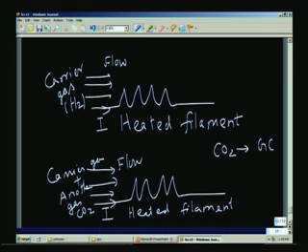So, the carrier gas, for example hydrogen, has a very high thermal conductivity, as you saw in the previous slide. We showed the high value for the carrier gas, but if I put a small amount of CO2 into it, the thermal conductivity will come down. Okay. The thermal conductivity will come down, and therefore, let us say K is higher here and K is lower here. So, suppose I say this is K carrier plus CO2, this is lower than this one.